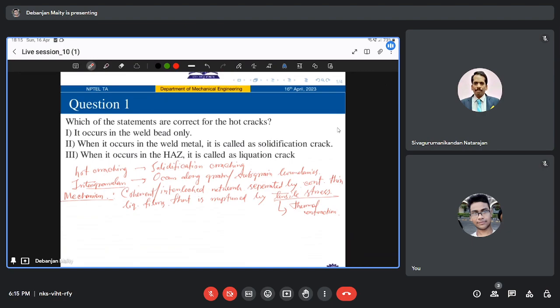The terminal stage of solidification, which I already mentioned as a characteristic, refers to the point at which the fraction of solid is close to 1, rather than the point at which the temperature nears the lower limit of the freezing range for an alloy. In some alloys, depending on the nature of the fraction of solid and temperature relationship, the fraction of solid can be close to 1 and essentially a complete solid network can form just below the liquidus temperature.